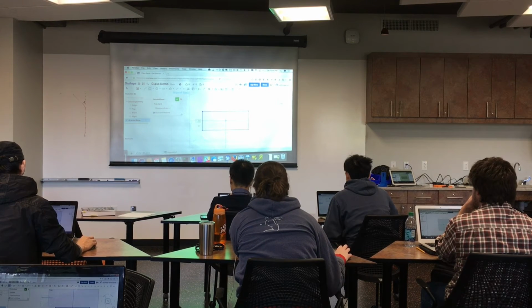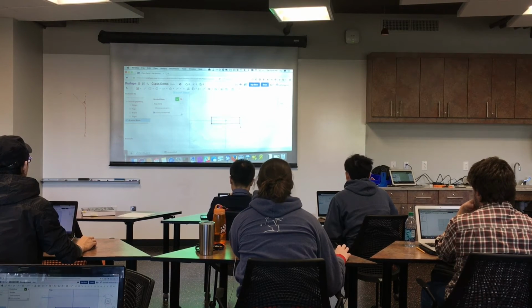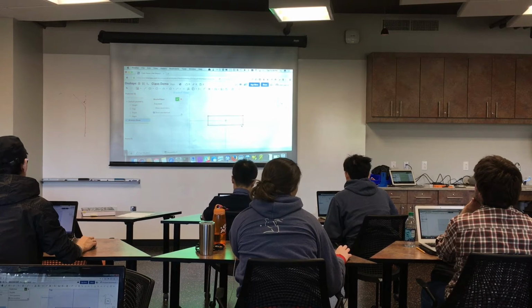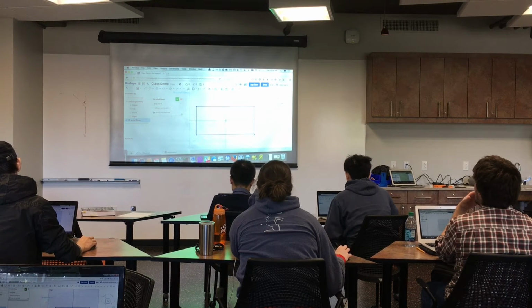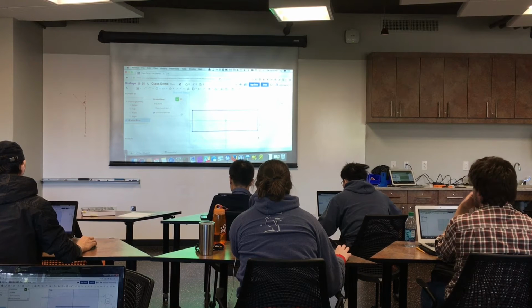And I'm going to hit escape. And now you see I have my mouse pointer back. I can grab these faces and vertices and change this right now. That means it is unconstrained. Blue lines mean that there is something unconstrained about this sketch, which is what you don't want in your part design. We want to have everything nice and tied up. But let's go ahead and create the rest of the geometry, and then we'll do some constraining.